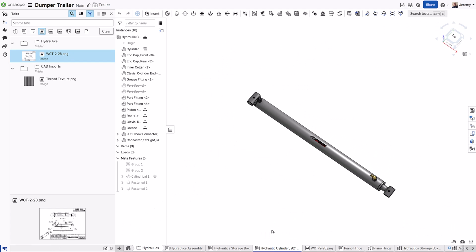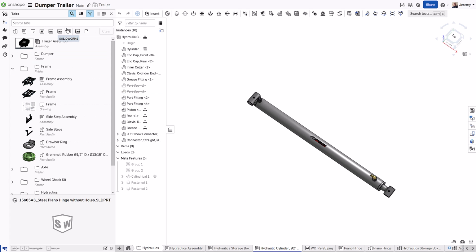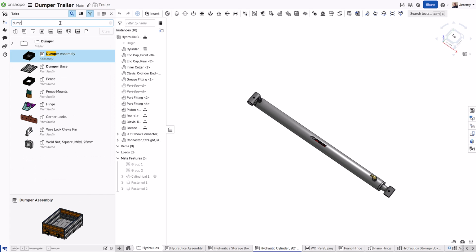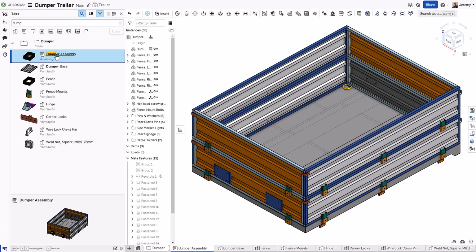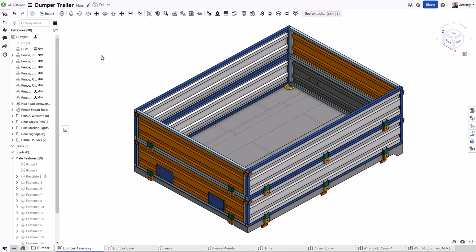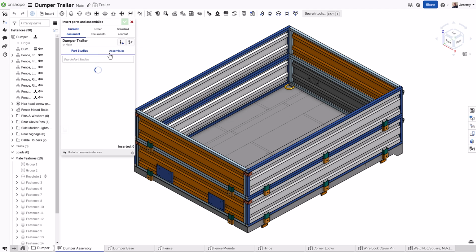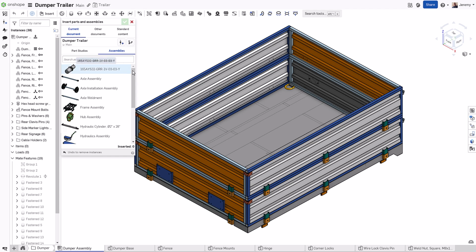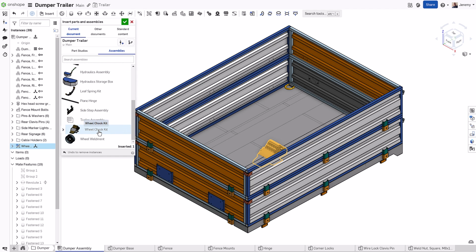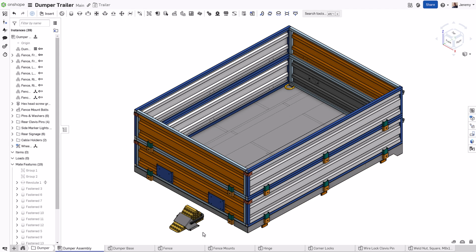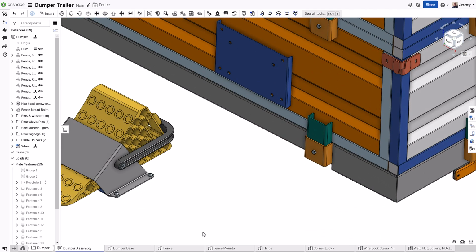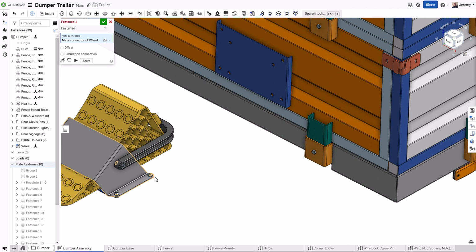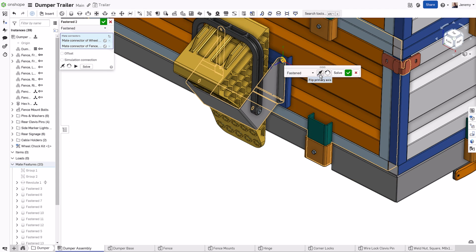To make managing and accessing this data easier, it's a good idea to familiarize yourself with the tab manager in the lower left-hand corner. This provides an easily sortable and searchable way to find the different parts, assemblies, and drawings within each document. As you are building your designs and assemblies, this single document makes it simple to quickly insert sketches, parts, and other assemblies into other parts and assemblies. You don't have to spend time searching for an existing component. Everything contained within the current document is easily accessible for reuse and incorporating into any part of your designs.